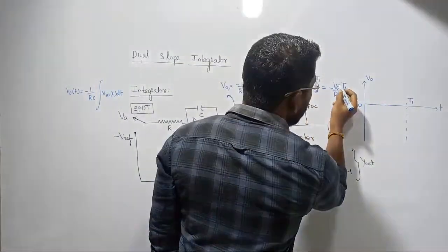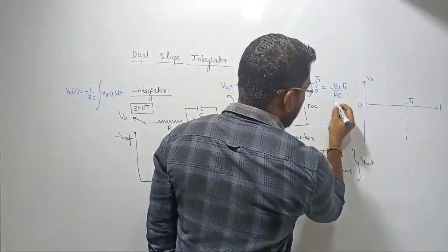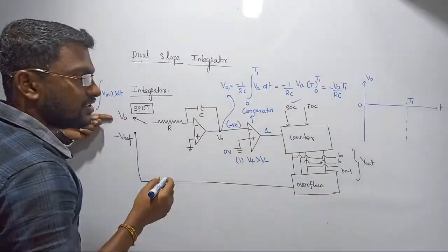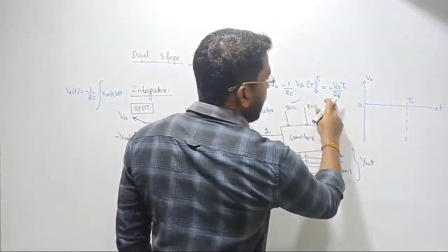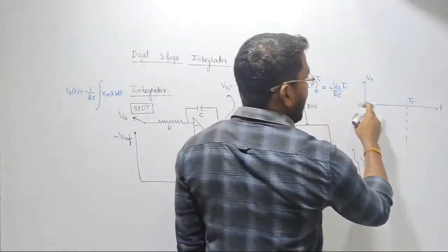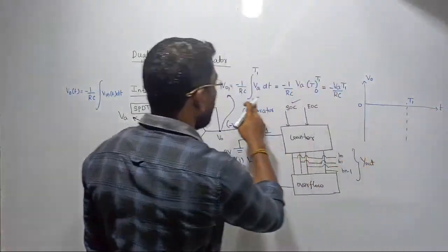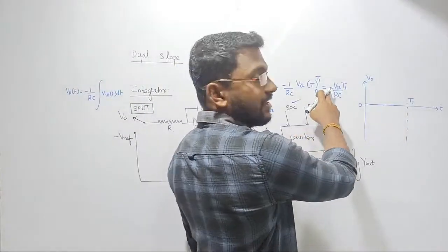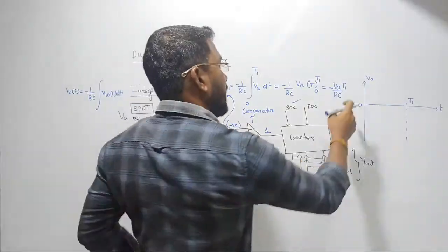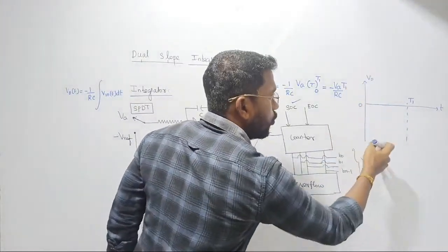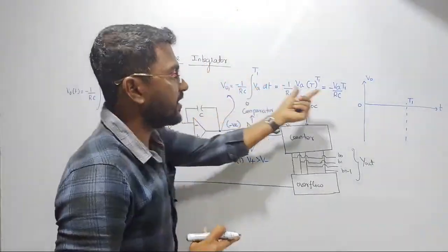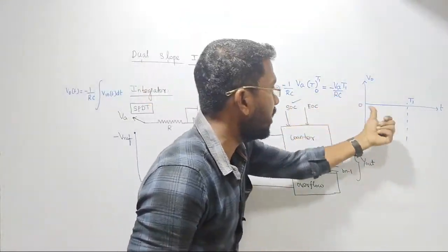First of all, see the voltage that we are injecting on the analog input side. So R and C values are fixed here, V also will be fixed here. Based on the time period, this is a positive time period only, but your voltage will become negative because it will be multiplied by minus. See, magnitude is negative, time period is positive. So we are lying in the fourth quadrant. First conclusion: voltage is negative, but time period is positive. We are lying in the fourth quadrant.